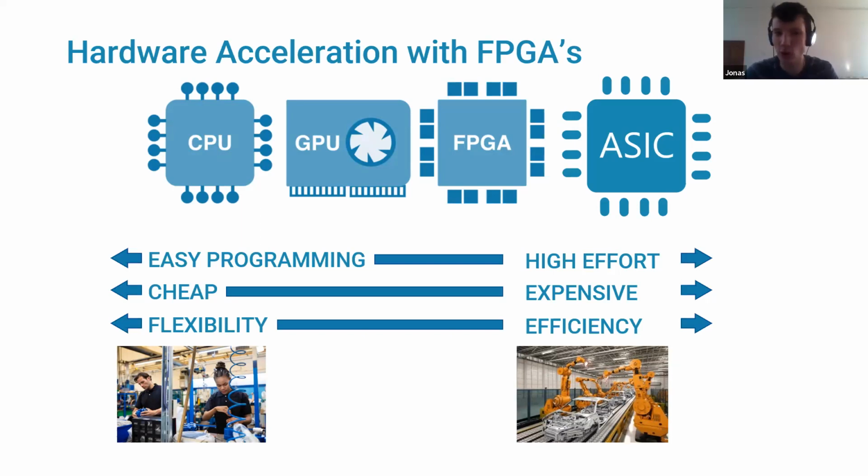But of course, the drawback is that once you have your HBM programming issues solved, it's going to be hard for a GPU to beat an FPGA, because an FPGA can have only the data path that you need strictly for an NTT, while a GPU is always going to have useless logic on the GPU. There's always going to be circuits on the GPU that you are not using for your number theoretic transform, because a GPU is not a circuit solely dedicated to doing number theoretic transforms.